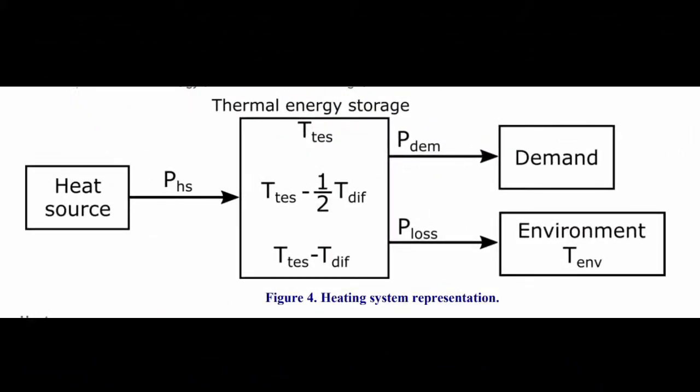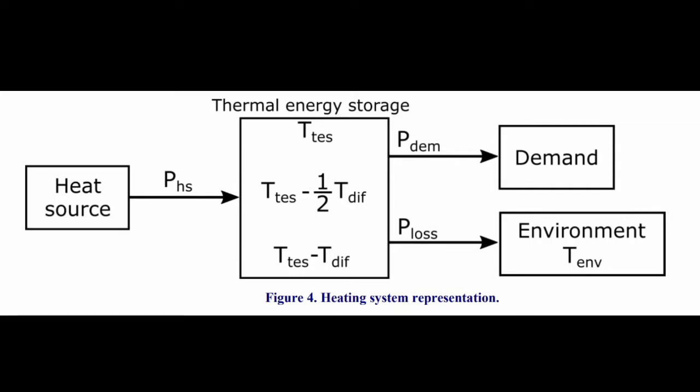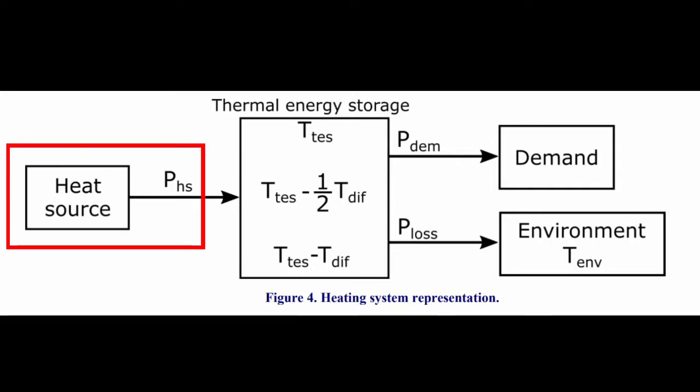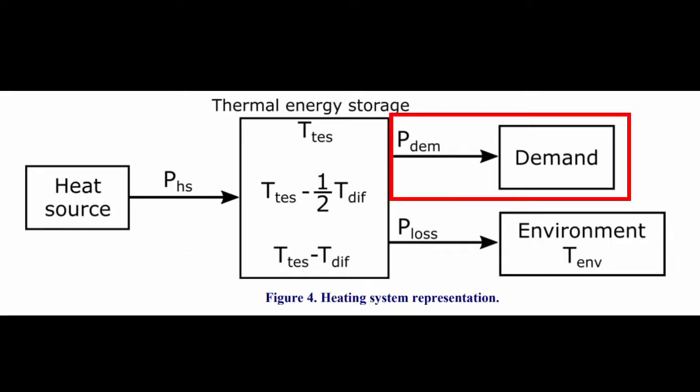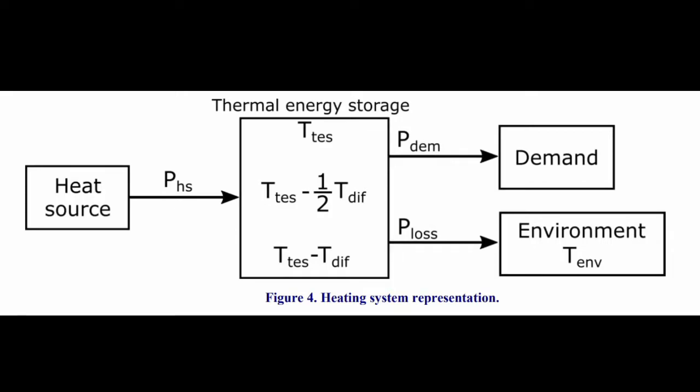The center point of the heating system is thermal energy storage. This thermal energy storage is assumed to be a cylindrical storage tank filled with water. It receives heating power from the heat source and provides heating power to consumers, that is, the demand side. It also loses energy due to temperature difference between the water in the tank and the surrounding air.